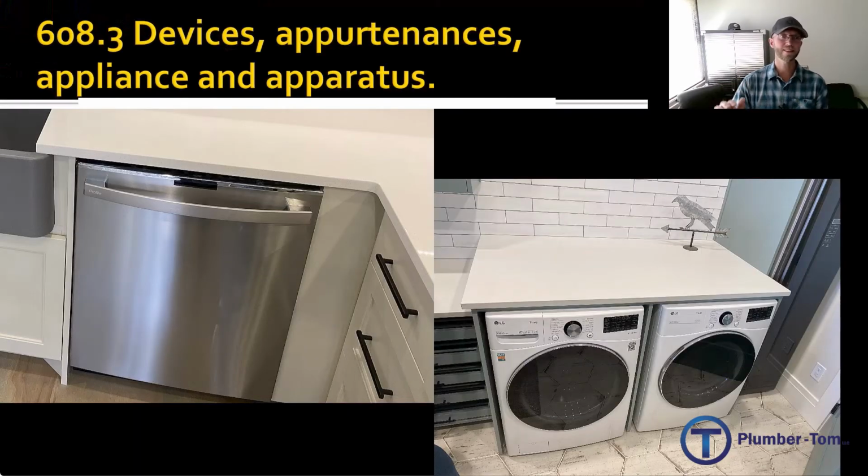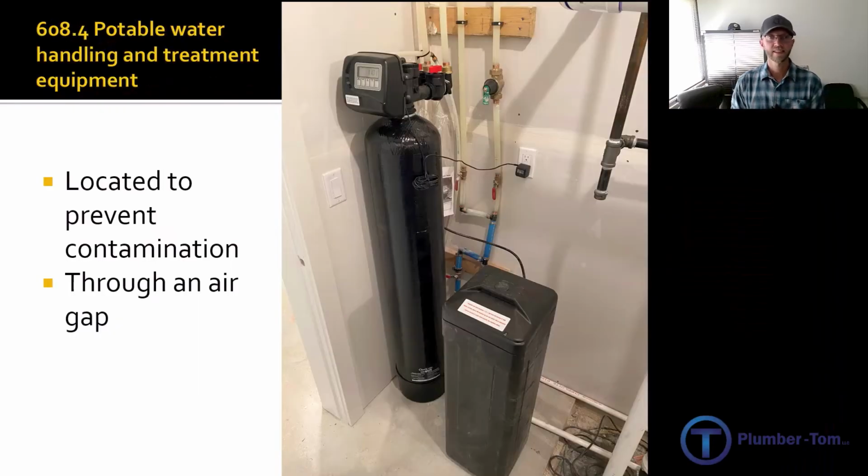608.3 talks about devices, appurtenances, appliances. Anytime you hook up a dishwasher, a washing machine, anything like that, there has to be a backflow prevention. An air gap is a good example. You can have an air gap fitting for a dishwasher. In Utah, we don't do that, but they allow us to do an air gap or an air break. 608.4, potable water handling and treatment equipment. Examples, filters, softeners. They have to be located so as to prevent contamination, and they do have to waste through an air gap. Softener drain connections particularly need to be through an air gap.